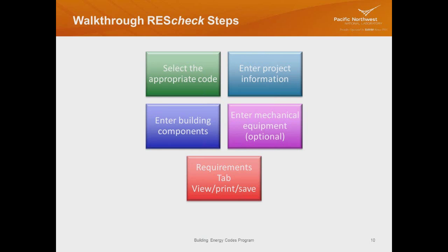And then there's a requirements tab feature that I'll show you, because all the stuff that you enter into REScheck is not the entire code. But what's nice about the software is that it provides you a list of all the other code requirements that are in the actual energy code, and then you will go in there and confirm that you're going to meet the rest of the provisions. There are mandatory requirements that are in the IECC, such as, in the most recent one, air leakage testing is one of them. So those requirements sit in the requirements tab, and they're not actual entries that you would enter into REScheck.